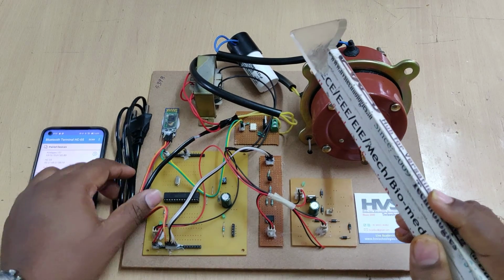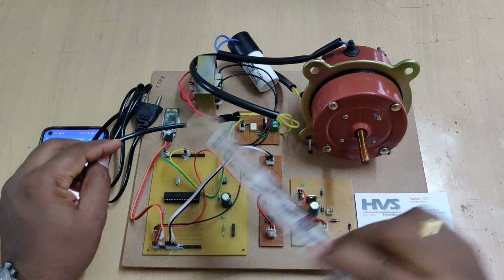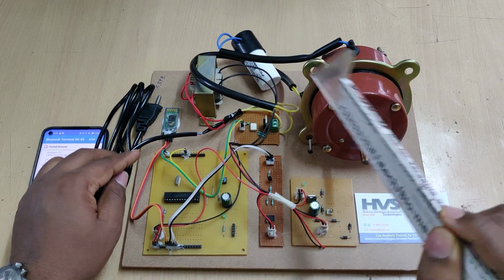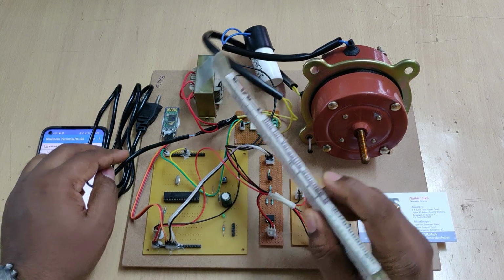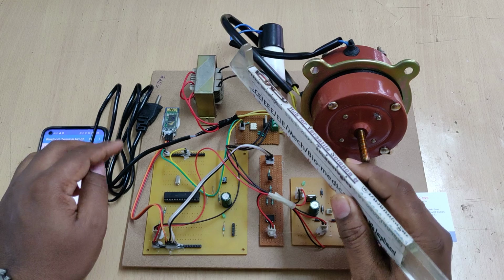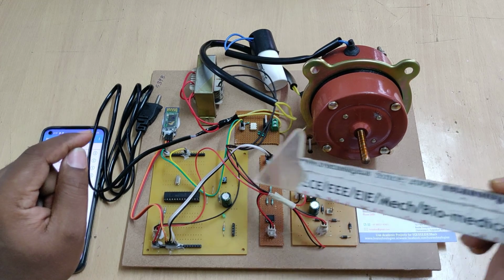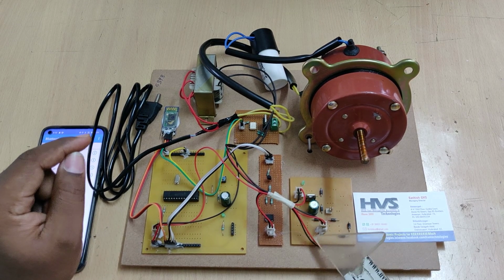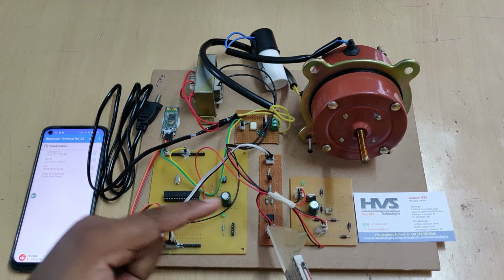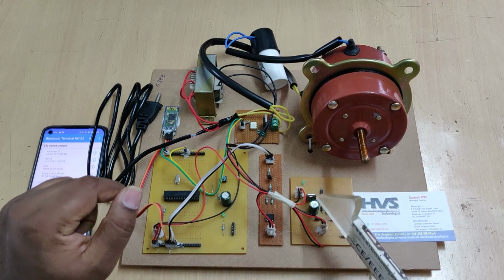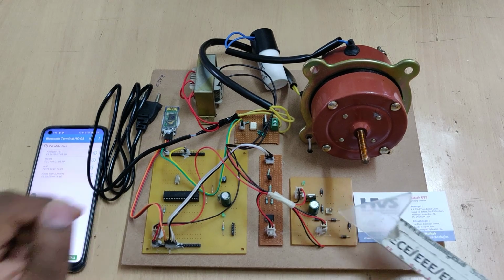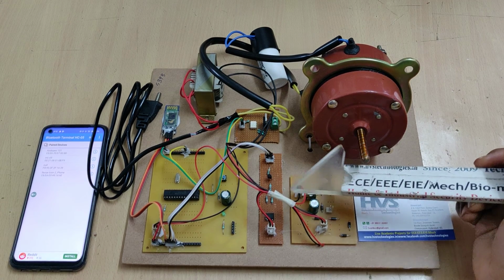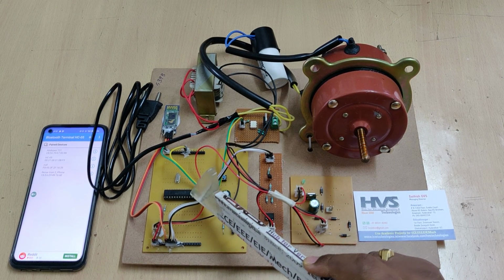Here the power flow is 230 volts AC input, going to the motor through this triac board. We can see that the triac is connected in series to the load, and next, parallelly, the input is given to the transformer. Here we are using a 0-9 transformer. The output of the transformer is 9 volts AC, given as input to this regulated power supply board. Parallelly, 9 volts AC is given as input to the zero crossing detector to detect the zero crossing timing. The regulated power supply board consists of 4 stages: rectifier, filter and regulation, and it gives a 5 volts output directly to the PIC16F73 microcontroller.